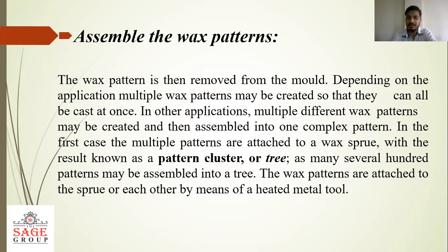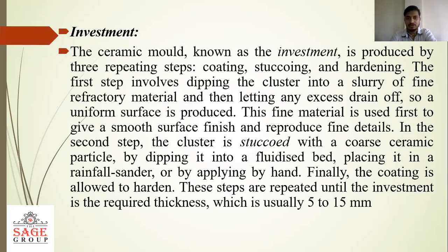In the first case, the multiple patterns are attached to a wax sprue, with a result known as a pattern cluster or tree. As many as several hundred patterns may be assembled into the tree. The wax patterns are attached to the sprue or to each other by means of a heated metal tool. So next one is investment.